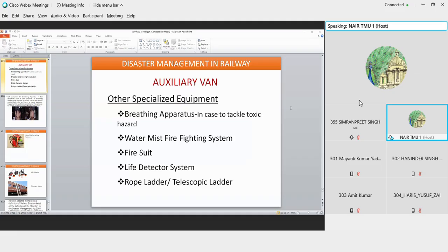Or assuming the two tracks are placed where they are supposed to maintain a gauge of 1676 and they are located with the help of Pandrol clips. The Pandrol clips are not fully tightened. The staff has not seen it. Because of a train which has passed, the impact of the longitudinal force comes in such a high pattern that these Pandrol clips have given up and the left rail or the right rail has moved away. So 1676 has become 1800. As soon as it becomes 1800, the wheels which are fixed at 1676 with the help of the axle will drop inside. This is called spread gauge.